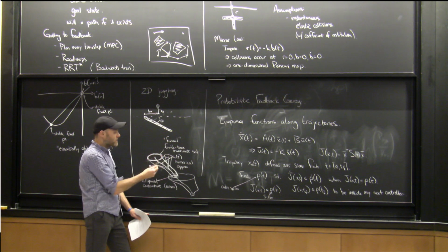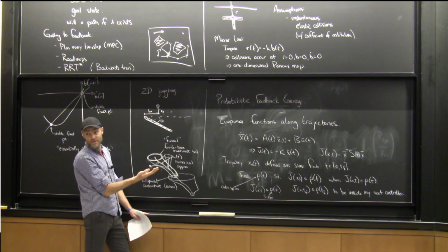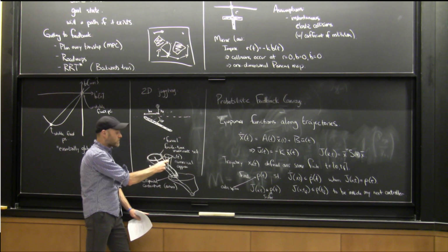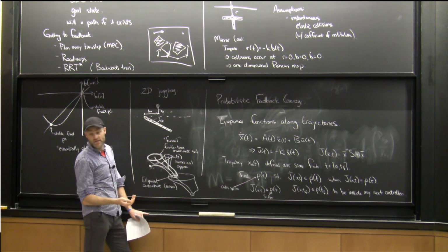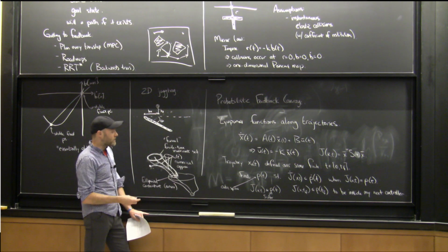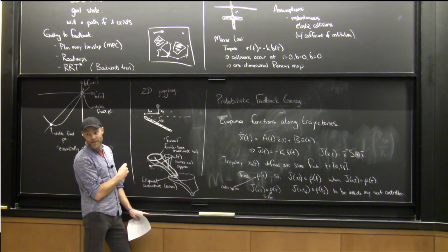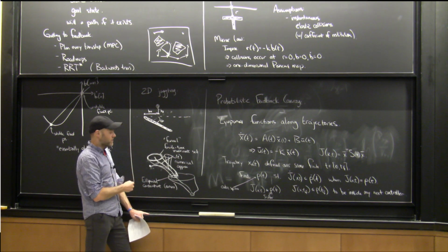And in practice, you can add new funnels to your tree while you're executing on the robot if you ever found yourself out of that, and trajectory optimization will often still work on the fly. And we have some ways where you can argue that that's actually a robust thing to do. Taken to the extreme, you could never call sums of squares to begin with. You can only do this sort of on-the-fly approach, and that's what the simulation-based LQR trees were.